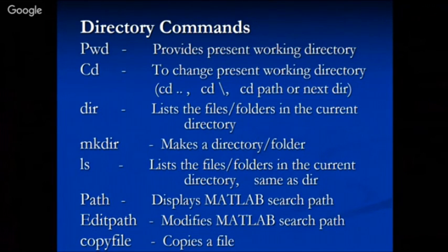Next is pwd, that is it provides the present working directory. Then cd to change the present working directory. dir to list the files and folders. mkdir, make a directory, you can write it as mkdir. Then ls, that is list the files. Then path, display the MATLAB search path. Then edit path, copy file.